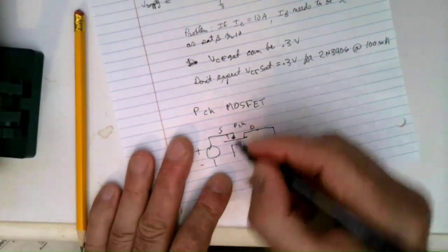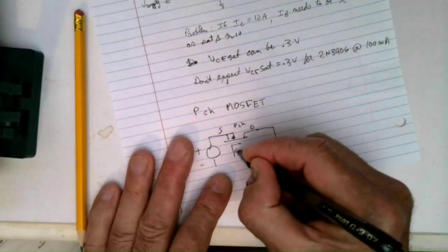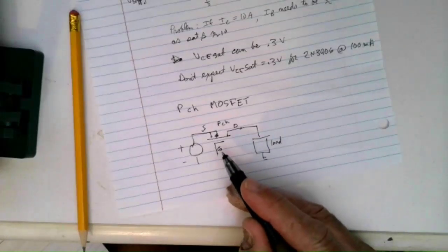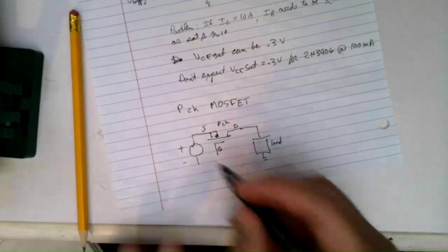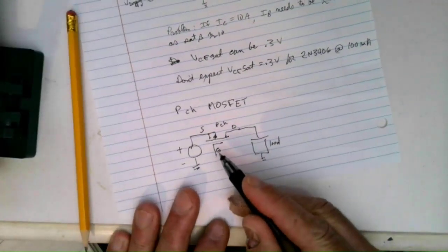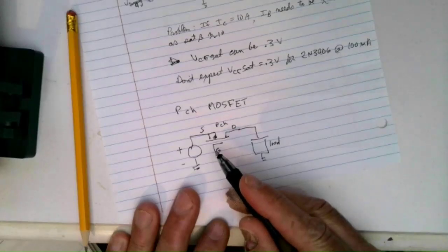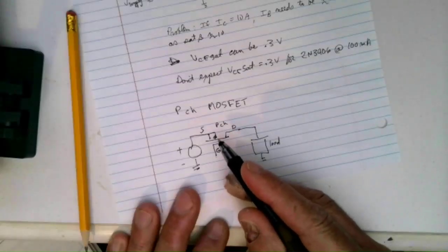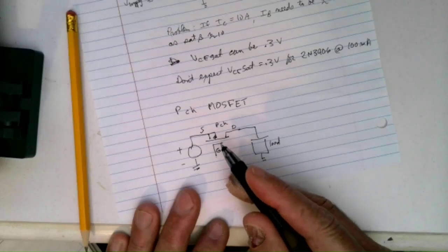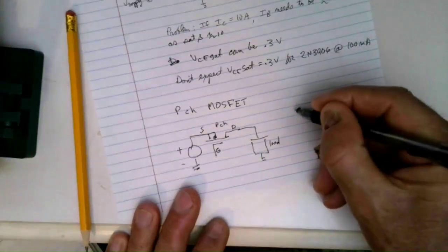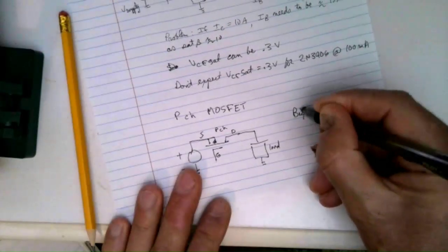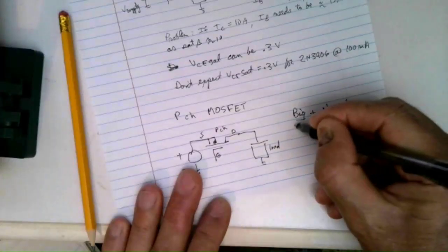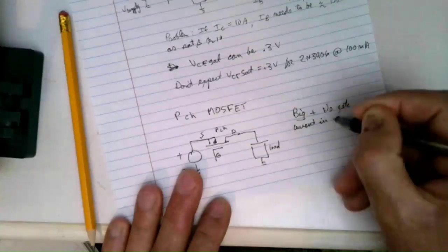And these are voltage controlled devices. Well, this is the gate. And they don't draw any steady state gate current. So if you want this in the off state steady state or in the on state steady state, there's no gate current to deal with. Now you've got to deal with some capacitance, some charge. You've got to move some charge when you want it to change state. But in the steady state, no gate current. So that's the big plus: there's no gate current in a steady state.